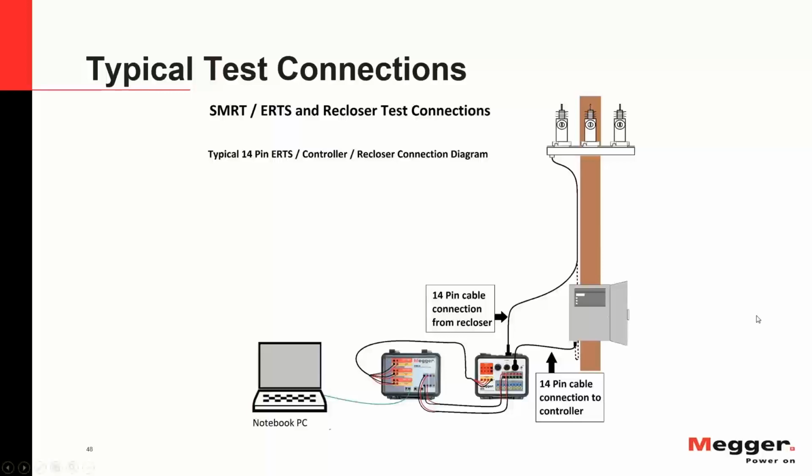So you have to be aware that you need to feed the relay with the proper breaker signals. Otherwise, the test will be compromised. You will not be able to do the test properly. Now, one way is like this. Again, bringing the signal from the unit into some test set and then feeding the relay. This way you can use analog signals from a test set, and you can use the digital signals directly from the breaker and feed it into the relay.